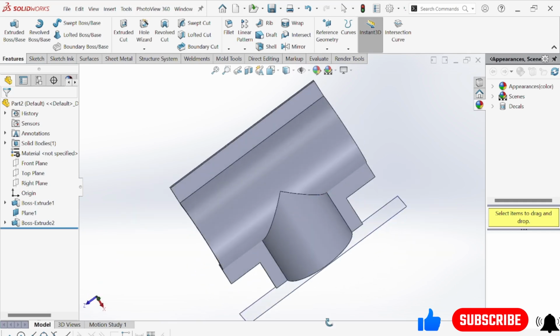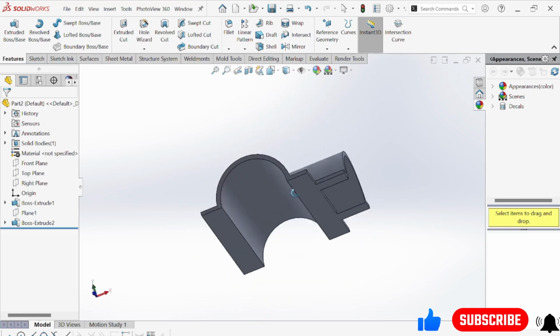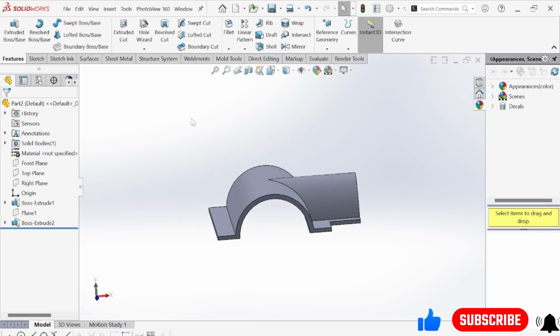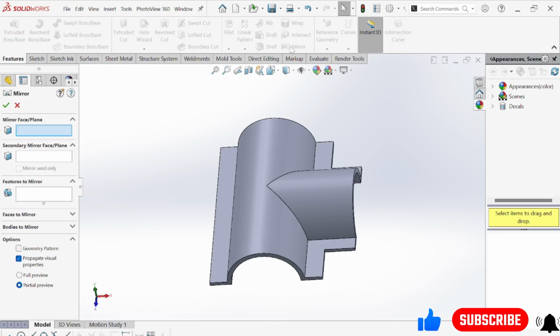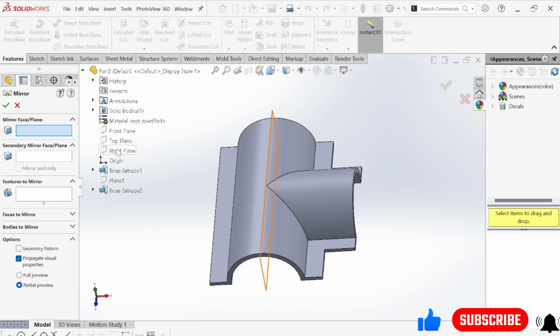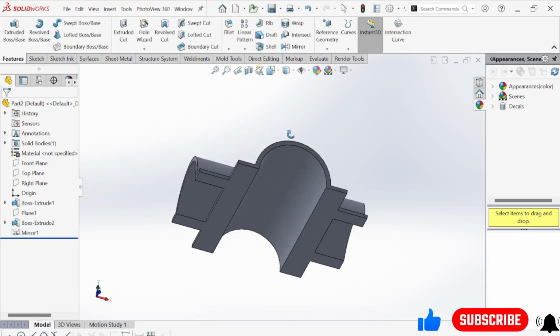Okay. So now simply hide this one if you want to hide, and better to hide this thing. Now come here. Find mirror entities in the feature section. Find right plane and this time select this one. Now here you see it gets copied, and simply make this one okay.